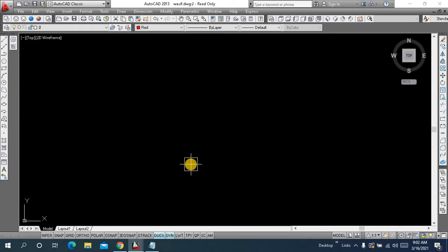Now the next thing that is really important for you people to understand is the status bar. This bar we call the status bar, okay? Now we will see the complete settings. For example, I draw a rectangle like this, okay? And again, I want to draw, but here you can see I can't snap to any of the corners. This means we have done something wrong, so we need settings inside the status bar. I will come to snaps, right click on the snaps, come to settings.